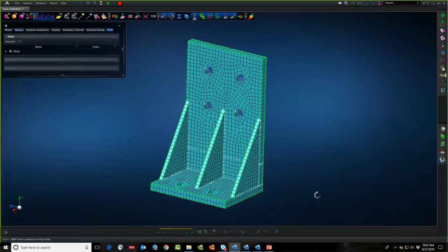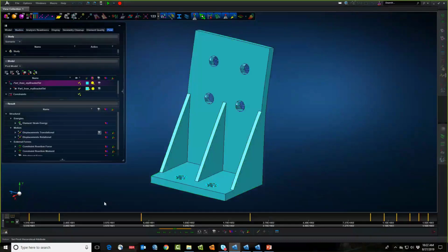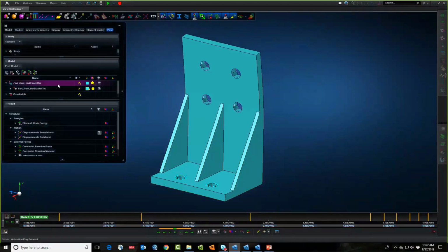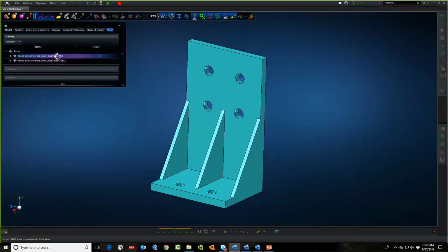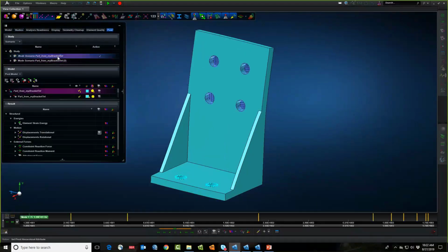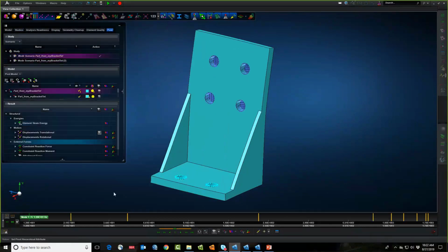And now we'll just look very quickly. And we can see that the first frequency is now 15.1 hertz. So I absolutely increased the frequency as I wanted to. And I can even go back and compare. So Apex has actually sort of kept a copy of the tap mesh behind the scenes so that I can actually just confirm, yeah, it was 12.9. You know, I did remember that correctly. And my change did increase the stiffness, which of course raised up the frequency.